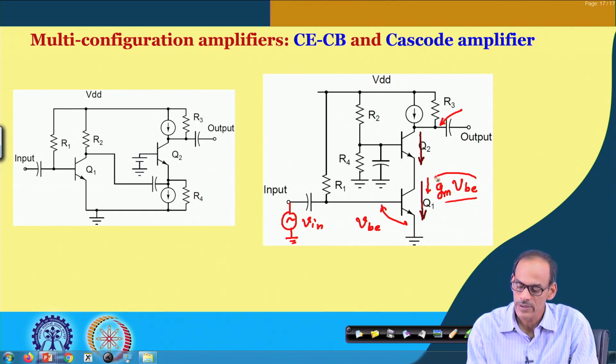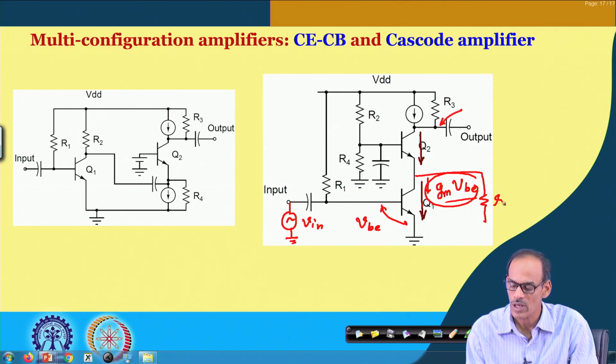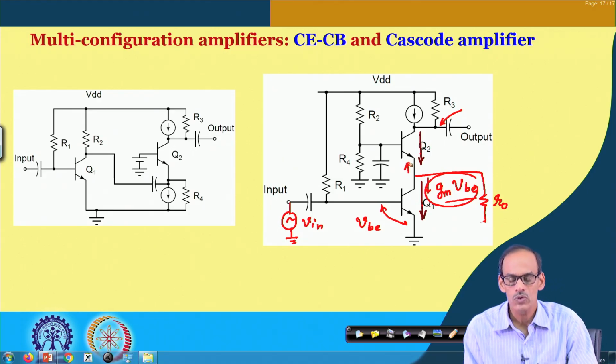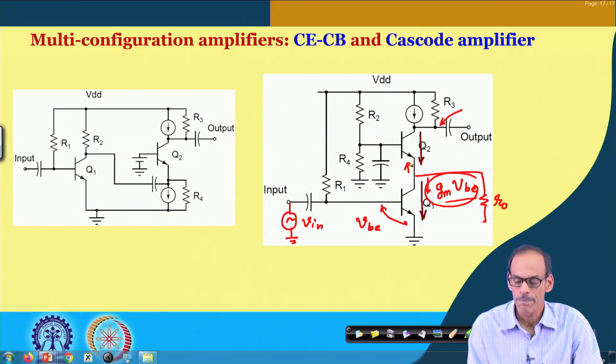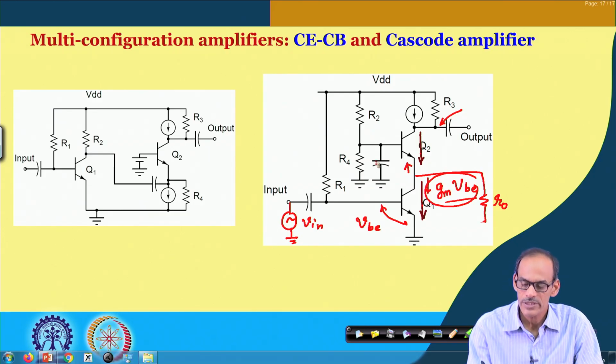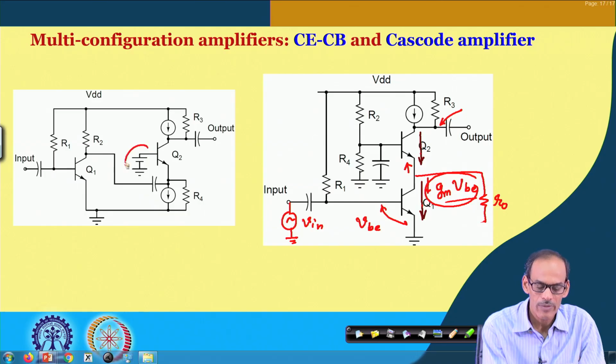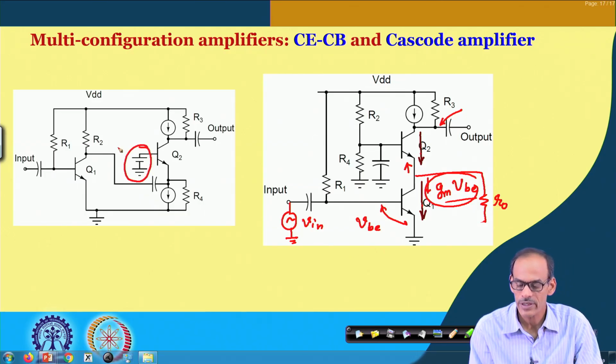So, this current source, of course, has its own conductance called RO, and this current is supposed to be successfully entering into this circuit. We will go through detailed analysis for that, but I would like to say that instead of having this ideal bias here, practically we have a potential divider constructed by R2 and R4 from the main supply VDD, which generates a DC voltage.